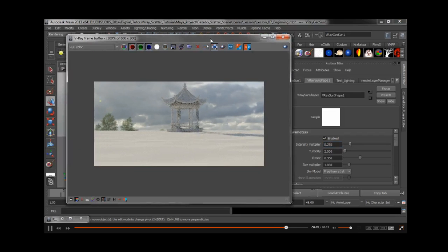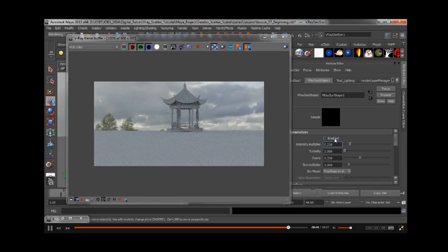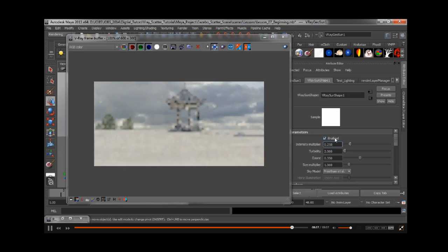What we want to get out of this is this additional shadow, which we did not have. If I turn off our HDRI, we can contrast up our HDRI and push it much further in the intensity to get a stronger shadow, but it's nice to get some reinforcement from the sun as well. So let's just let this clear up here. Even at 0.1, we'll still get the shadow and the lighting won't be affected too much. So I think we'll leave that here for now.